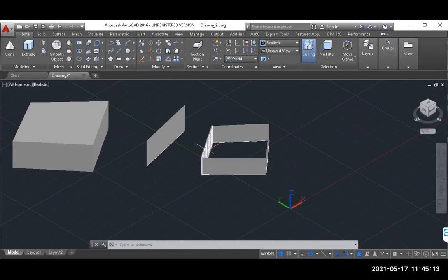So I hope you understand when and how to use this region command, because I have seen in laboratory sessions many students make this mistake. Suppose they have to create a box, they draw a rectangle or a square using the line command and they extrude it, and they don't obtain an object like this. Instead, they get an object like this, boundary surfaces. So before extruding, if you want to create a box-like object, then you have to use this command region. I will write here in the command line. You can keep a note of it in your notebook. This is a very, very important command.